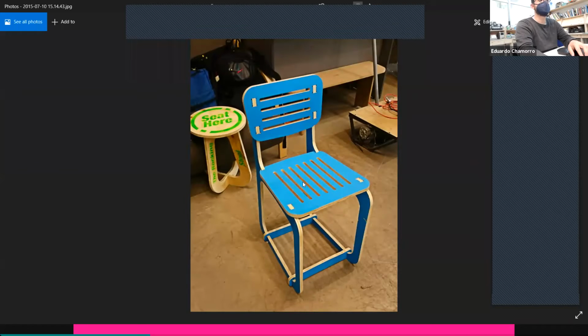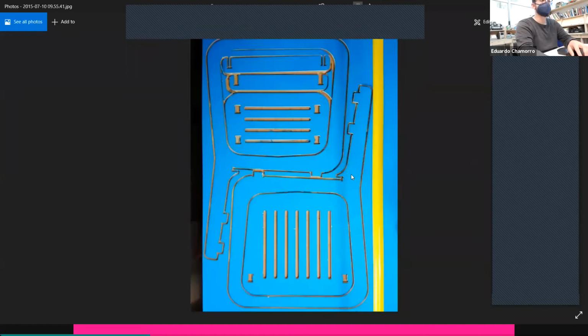If you account already for the material that you are eating with your end mill, this depends a lot on the tool you are using. You can cut, uncut, and produce 2 cuts in one. You can save a lot of time because you can merge 2 cuts into one. The same happens in the laser cut. You can cut with just one line. You can cut with the left part and the right part. You don't need to cut them twice. And it's quite important in the CNC. You don't want to overcut things that you already cut.